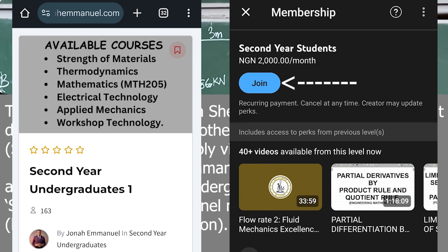For bending moment, again, listen and take note. In my shear force, I had negative values. I came down here. Please check. In bending moment, do you have negative values? Look at x equals 0, 2, 5, 7. Any negative? Since there are no negative values, I will take the datum at the very bottom. Why? I am not expecting a negative value.